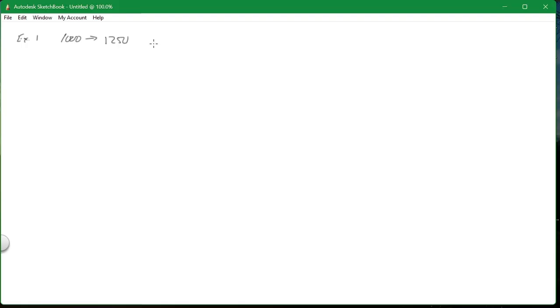Okay, so example, and then the first one is the I full load primary, and that would be 52.3. And then the I full load secondary, I got 1,503. And then for the I fault secondary, I got 30,060 approximately.